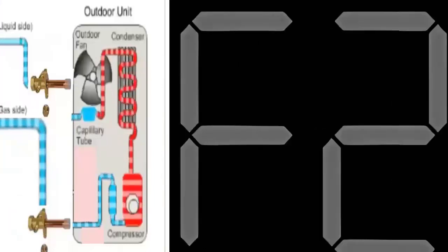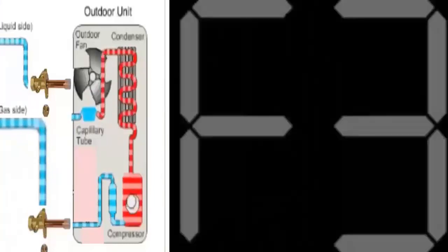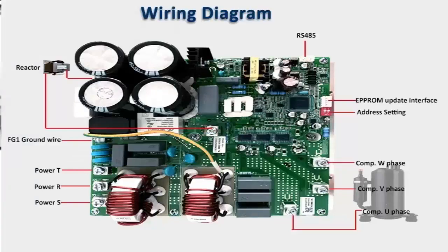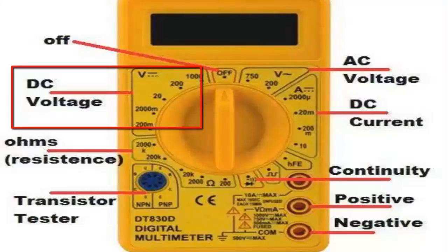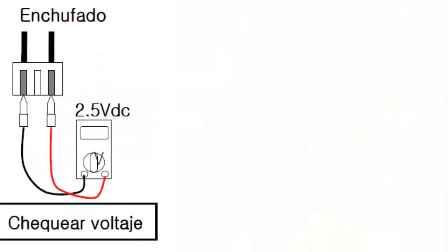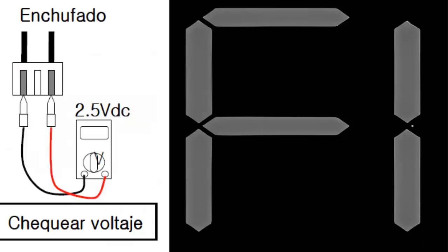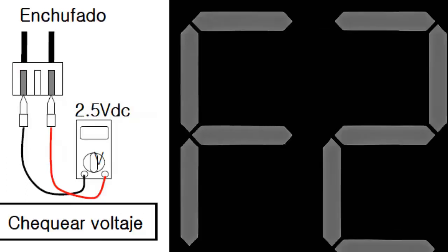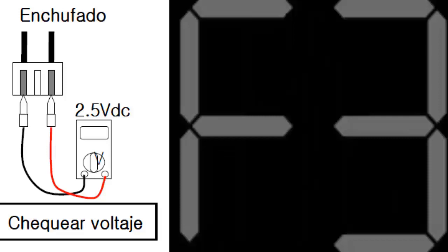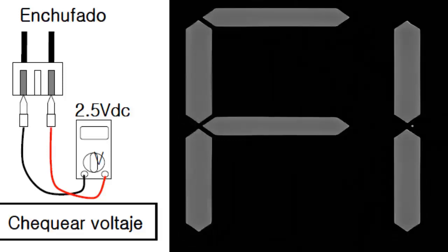8. If the measurements indicate that the sensor is electrically fine, focus the study on the sensor's power supply. 9. Connect the sensor, turn on the equipment using the multimeter on the direct current voltage scale, and measure if the electrical power of the sensor is correctly close to 2.5 V, otherwise, the damage could be in the external board.